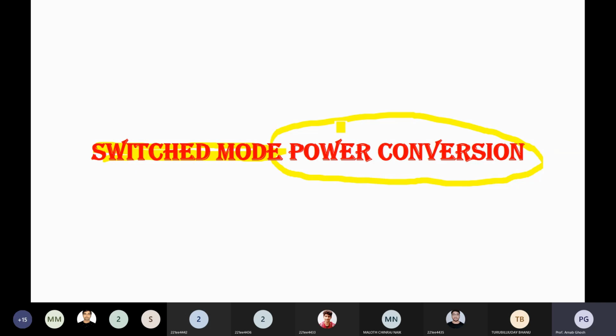Okay, that's the motivation for switch mode power conversion, the switch mode operation of power electronics devices. What type of devices? There are different types of devices: controlled devices, uncontrolled devices, semi-controlled devices. As per the devices, a diode is a basic example of an uncontrolled device, and those having a gate terminal or base terminal are all controlled devices. Again, the controlled devices may be segregated into voltage control devices or current control devices. So it's about the device physics.